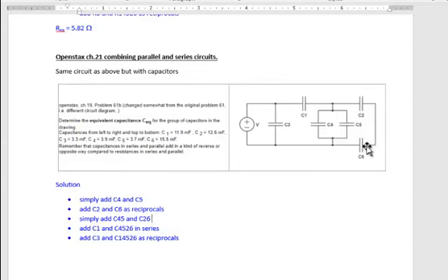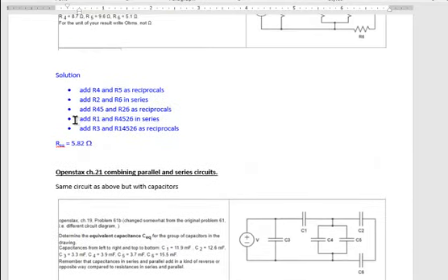this one here and this one here because they're in parallel as capacitances. Then C1 and all the rest here are in series, so as capacitances, they're added as reciprocals. And then finally, all the stuff here on the right-hand side is in parallel with the C3, so they simply add. And so what I should have done earlier on this one here is, instead of saying add them and then series, simply add. There we go. And again, resistors are different, or just turned around, doing the opposite thing as capacitors do.